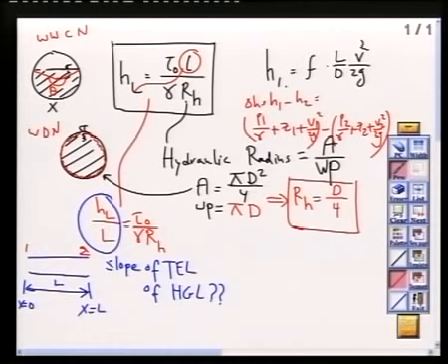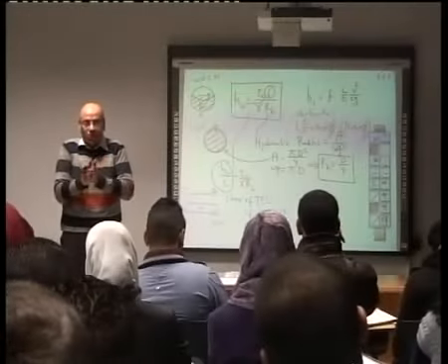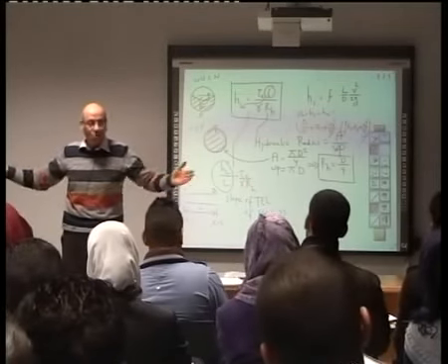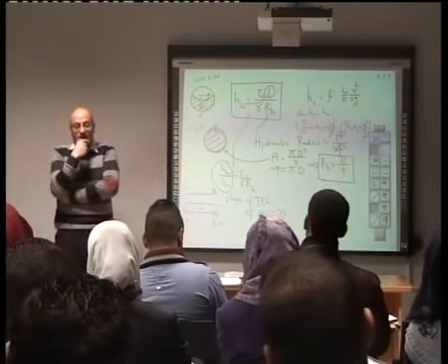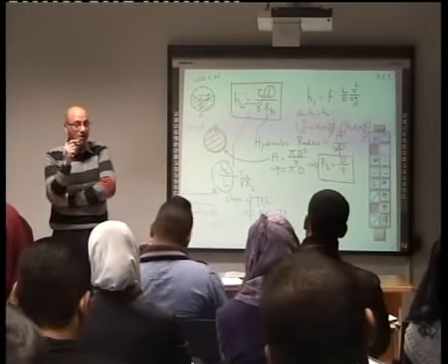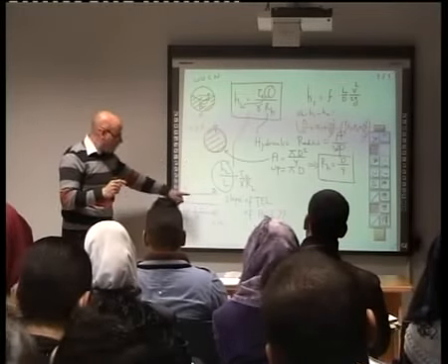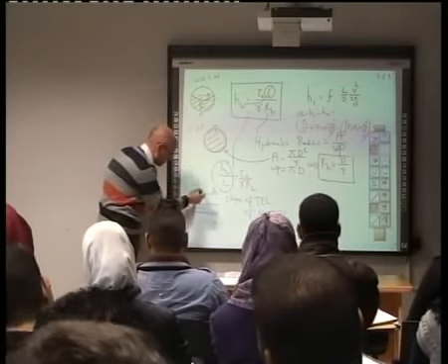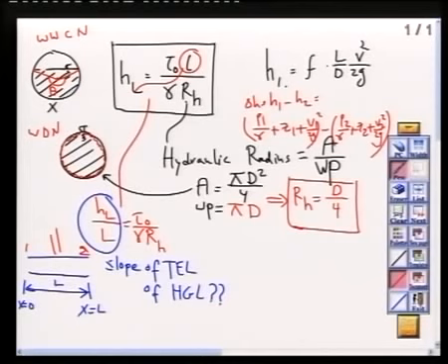But if this is a pipe with constant diameter and not a varying flow, how can the flow rate vary in this pipe? Diameter change? No. Well, flow is flow. You can make the flow in 1 inch or in 10 inches. Like if you have 10 people, they can enter through this door or 2 doors. Doesn't really matter. I mean, Q is Q, but the velocity might change. That is the point, but we are talking about Q. Now, Q can only change in this case if there is another pipe connected, so part of the flow is being lost, but this is not really the case.